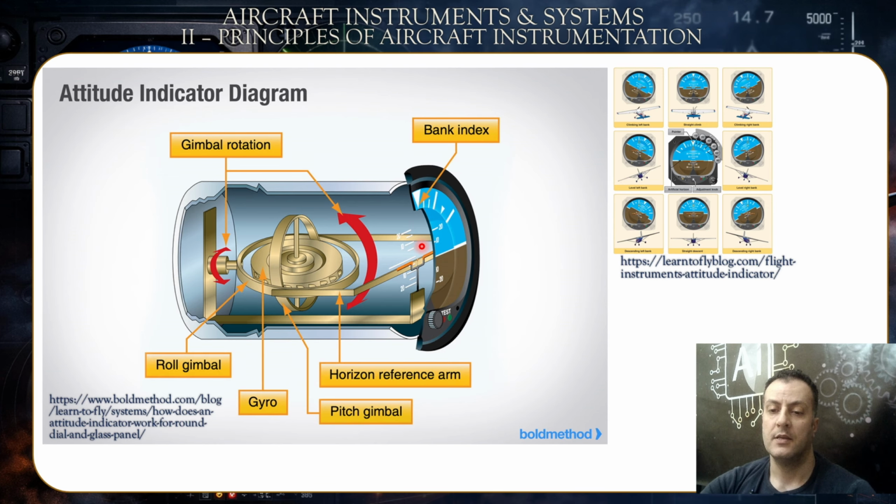Okay, so when it comes to the roll, we've already explained it. These are the degrees for when the aircraft is rolling. So the roll would be measured, and also the pitch up or down. When it's pitching down, you would have this reference going downwards.